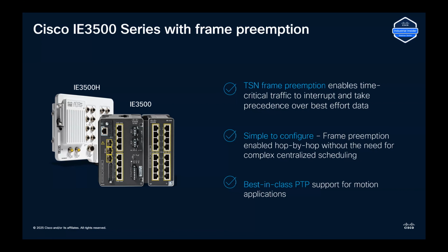It allows these control frames to go even before the previous frame has ended, so it takes precedence over the previous frame. In that way, you can at least reduce latency and jitter, and make sure that your PLCs, even though they might be far away from the machines they're controlling, are still very effective.